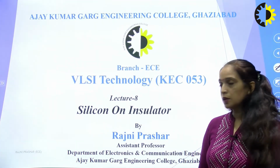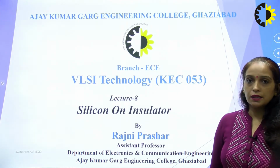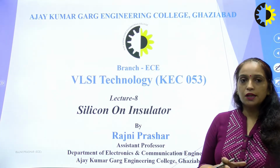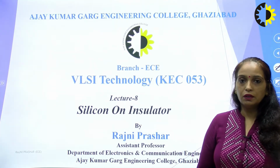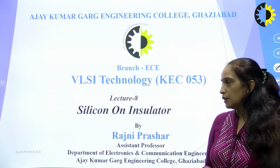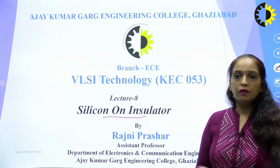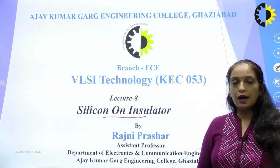And second, when we decrease the transistor size, going from 180 nanometer to 45 nanometer or 28 nanometer or beyond, short channel effects come into the picture. So it is not possible to get good transistor performance with simple CMOS fabrication steps. The topic of discussion today, silicon on insulator, will tell you how we can fabricate devices over a silicon wafer with enhanced performance.